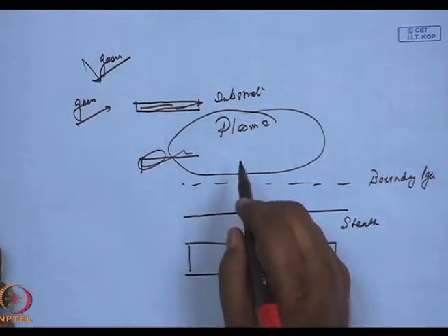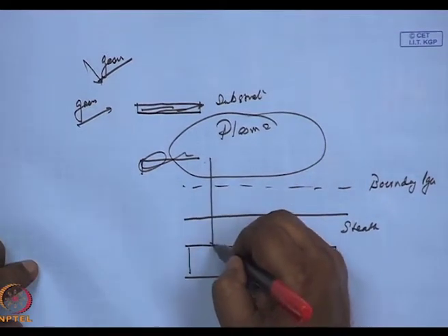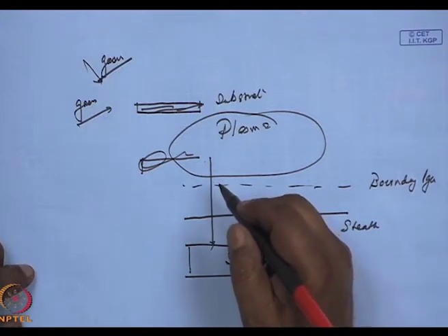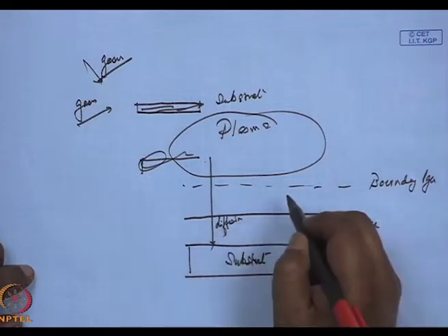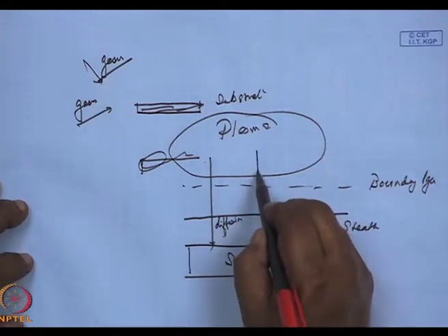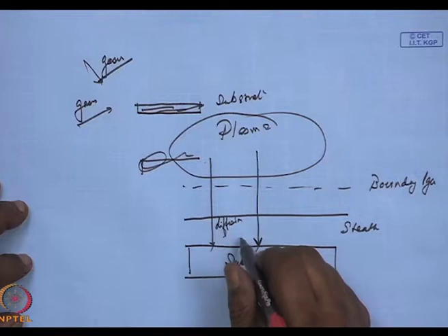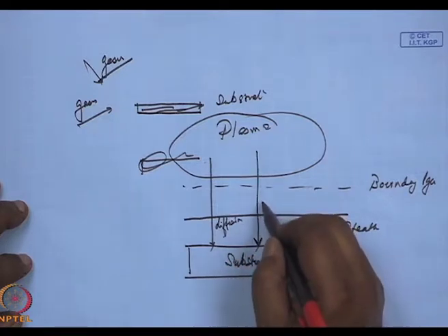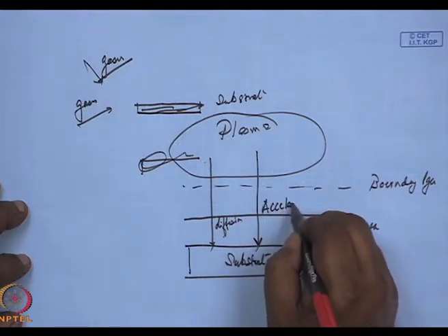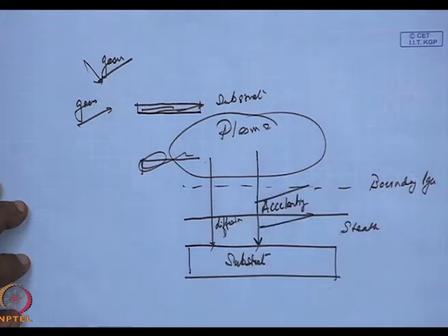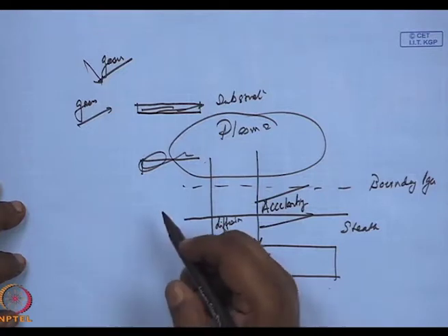What can happen? The neutral particles can come and hit the substrate. They will come by a diffusion linked process. If there are ionic species, they will also come and hit the substrate. Here I have the advantage that I will have the ionic species accelerating so that they come and hit with a significant force.